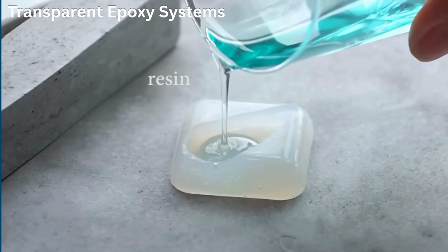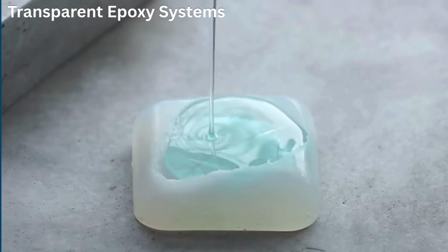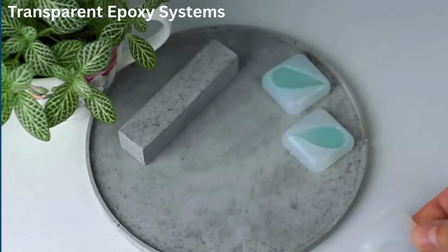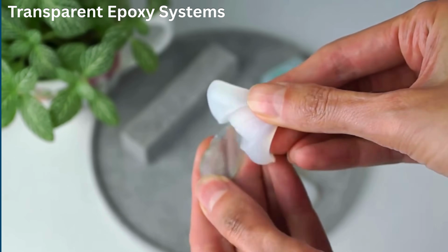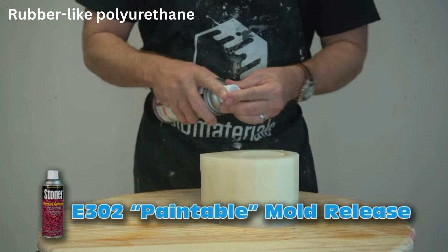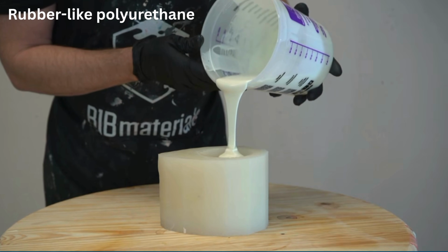Epoxy resins provide superior stiffness, dimensional stability, and thermal resistance, making them suitable for tooling inserts, electrical encapsulation, and structural components. Transparent polyurethane and epoxy systems are employed for optical components such as lenses, light guides, and display covers owing to their excellent clarity and smooth surface finish. Rubber-like polyurethane elastomers mimic thermoplastic polyurethane (TPU) or silicone rubber and are commonly used for seals, grips, vibration dampers, and soft-touch components.